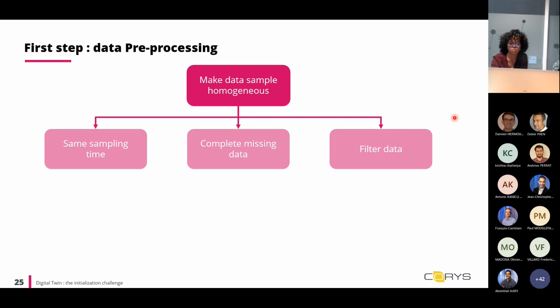The first step is to impose the same sampling time on our matrix of data given from the plant. For that, we are just going to place some empty boxes in the vector for each measurement that corresponds to each time step and sampling step for each of our measurements. So in this case, 25, 23, etc.